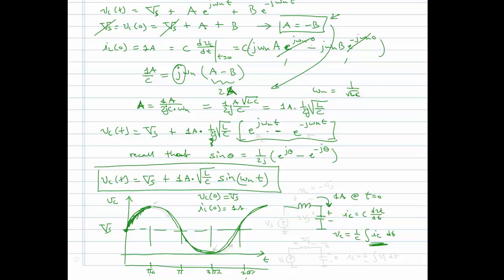Eventually what happens is at this peak here, the voltage across the capacitor ends up being 2 Vs. And at that point, because we have Vs over on the left side, the voltage across the inductor at that point ends up being minus Vs. And what begins to happen at that point is there's a sufficient negative voltage across that inductor that it slows the current down.